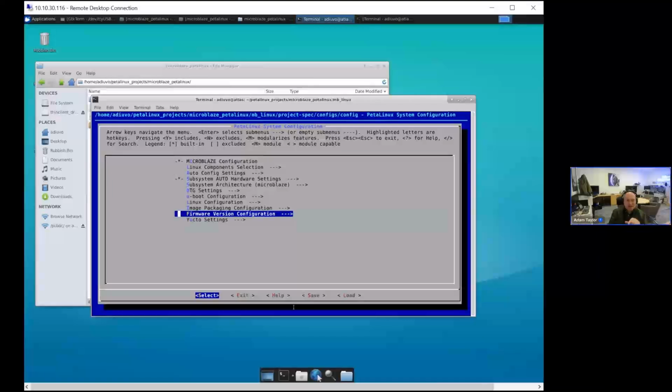That's a good question. You can use eMMC provided you've got a driver for eMMC, because you'd need to create the interface in your programmable logic to do that. If you're using a Zynq or MPSoC or a Versal, then yes, sure, you can do that. With the MicroBlaze, it's a little bit more constrained.